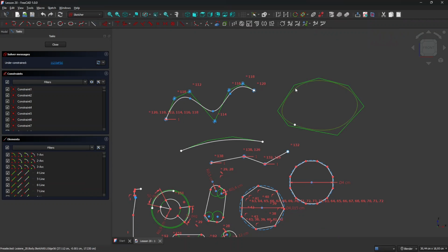And also this one here, let me select. Here you can activate the visualization of the single vertices, so you can modify the curve. Now the control vertices are outside, and the interpolation points or vertices are inside a curve, and you can use both if you want.